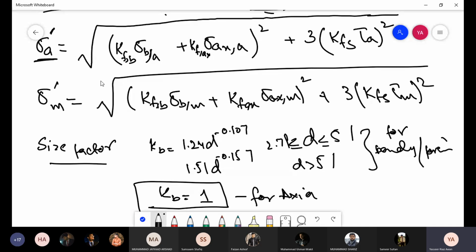Now when you have a combined load, you have combined sigma a and sigma m using distortion energy theory, but when you are finding the endurance limit, the problem arises of which equation to use, because we have both bending and axial cases, okay? Both bending, torsion and axial cases. So we use Kb from this equation rather than equal to 1.